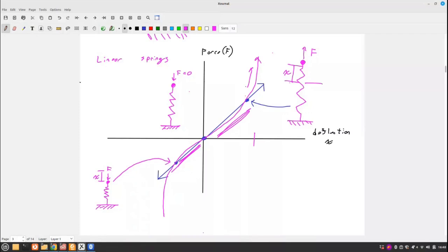This is not like a spring yielding, but maybe you have a specially designed spring where a certain amount of the spring enables it to act relatively passively. And then once you hit enough deflection, you want it to get stiffer. And that's what a nonlinear spring is. And there's lots of different ways you can design nonlinear springs, or really all springs are nonlinear. But we can typically model enough springs as linear over enough of their range to make them useful.